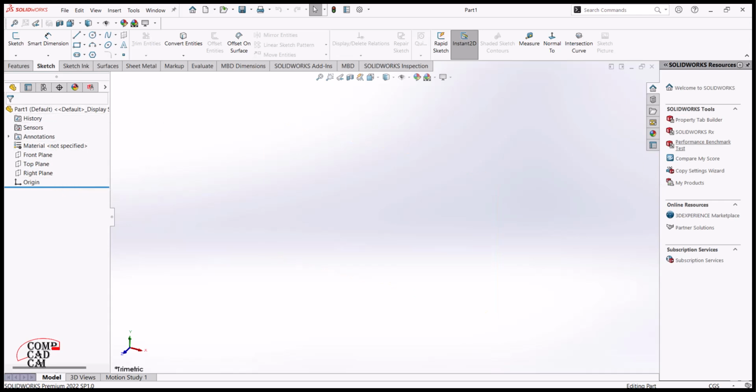Then on your right down here is where your unit of drawing is, the unit of measurement. So we have millimeters, kilogram, seconds. You have centimeter, gram, second, millimeter, gram, second, inch, pound, second. So if you want to draw in millimeters, which is this one, you just select this one, then it is automatically selected. If in inch, pound, you select inch, pound. If it's in centimeters, you select centimeter.